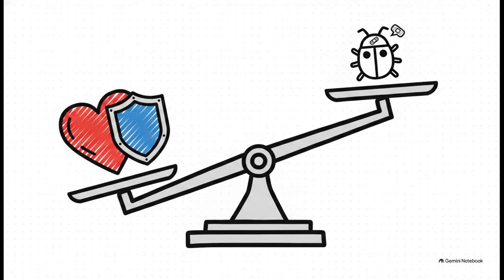When analyzing these systems, engineers have to categorize risks. On one side, we have intolerable risks. These are direct threats to human life. Going back to our insulin pump example, a massive insulin overdose is a completely intolerable risk. As engineers, you must prioritize preventing these at all costs, designing fail-safes so they literally cannot happen. On the other side, we have ALARP risks, which stands for as low as reasonably practical. These might be less serious hardware glitches that could cause, say, a minor delay, but won't physically harm the patient. We minimize these as much as our budget and schedule practically allow, but intolerable risks always come first.